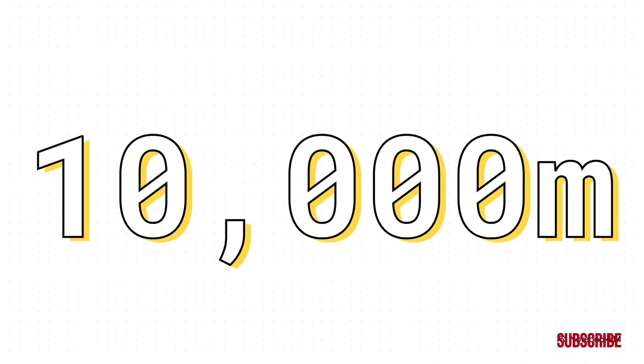If you tried to transmit low-frequency human voice without modulation, your cell phone antenna would literally need to be thousands of meters tall. We're talking up to 10,000 meters. No way that fits in your pocket. Modulation increases the frequency, shrinks the wavelength, and keeps our antennas wondrously small.